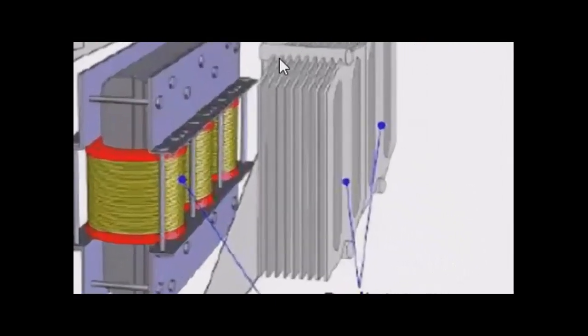These cooling fins have openings within them. So the function is actually to spread thin the oil molecules so that we'll have as much surface area contact as possible with the fins that will conduct the heat away from the oil molecule. As the fins conduct the heat away from the oil molecules, air molecules that are trapped around the fin outside the transformer will conduct the heat away from the metal, which will now be the molecules of the fin material, which will be hot on the external side. The air molecule in contact with it will conduct that heat away from the